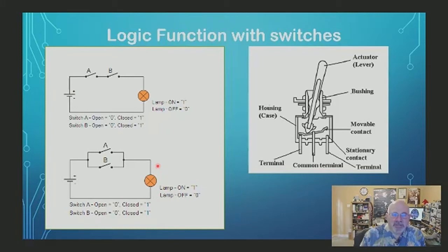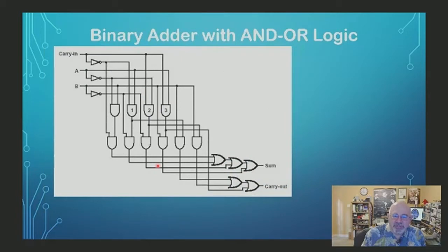And we can make this more complex. And that's how Boolean logic and binary algebra starts, because we can start putting together complex functions, like doing a binary adder. So this is very simple because it's only 2 variables, again 2 states, 0 and 1. And if we want to add the value of A to B, we just build this circuit using logic, and then this is the sum. And what happens, it's only 1 digit.